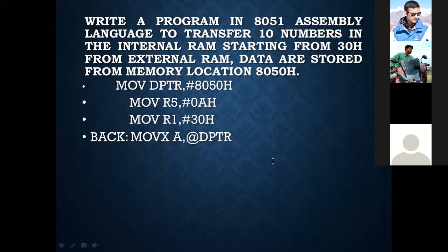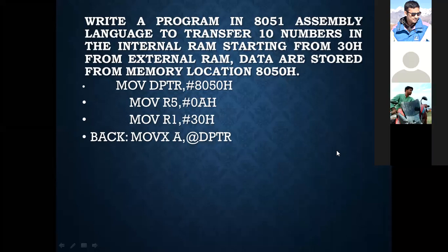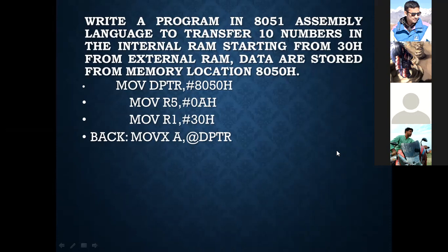Monica Nagar. Sir, external memory moved through accumulator. External memory has been moved to accumulator. Is that so? Is it correct? No, sir. The content at the address of DPTR will be moved to the register A.